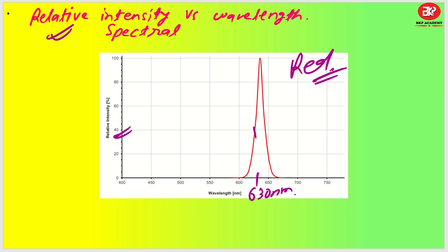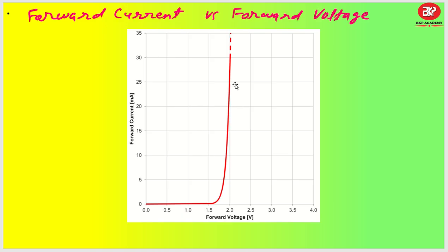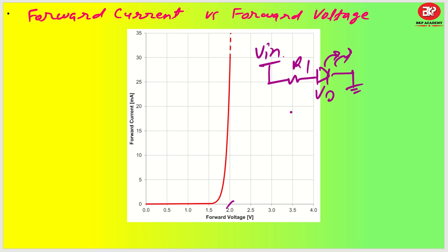Okay, similar to that, we had the forward voltage drop that I told you about. If you give a 2-volt drop across the LED, then it will be properly illuminated. So you have to make sure the resistor and the LED design are such that your V input minus this VF, divided by R1, meets this spec. Okay,